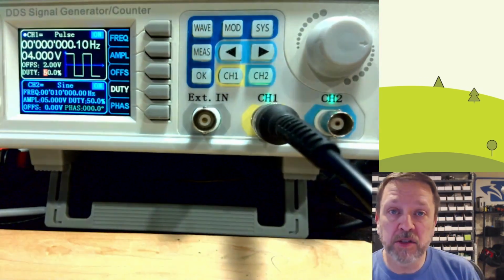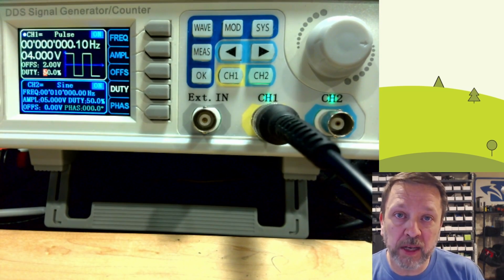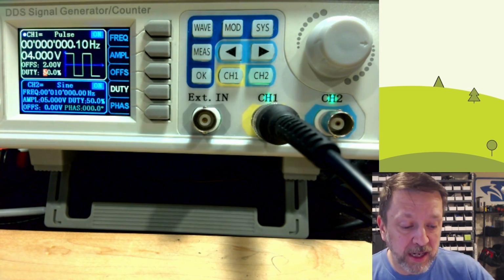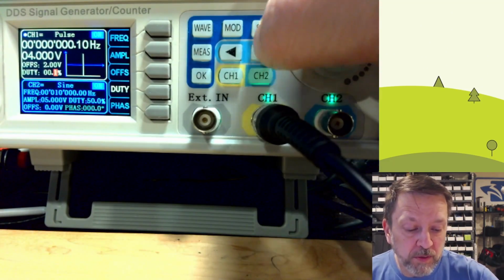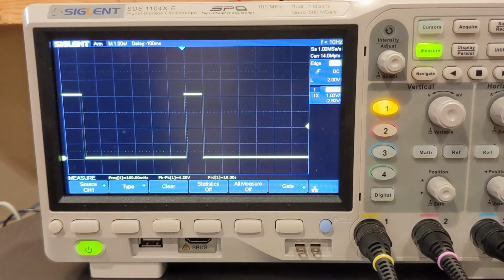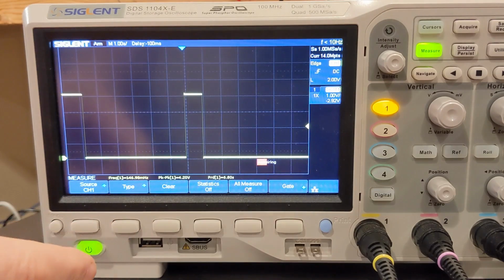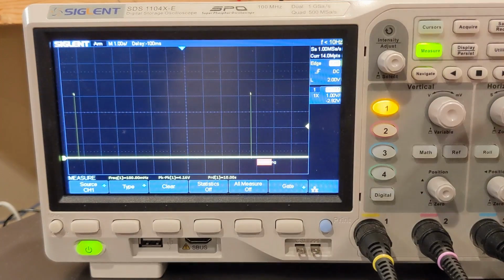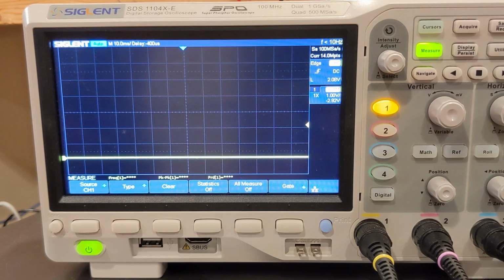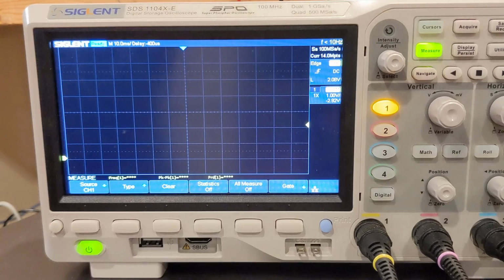Now, the duty cycle here depends on what the button click does in your application. If you press it and it pulls high, you could then adjust your duty cycle to 0.1%. So we're going to get this very quick pulse, 1/10 of a second, so 100 milliseconds, every 10 seconds. You can see that pulse. And if I move one over, we're only getting one every 10 seconds, remember? So there you go. Oh, let me adjust that. And so we'll capture this pulse.